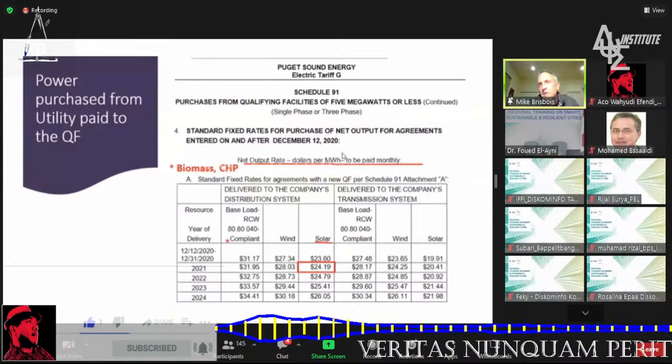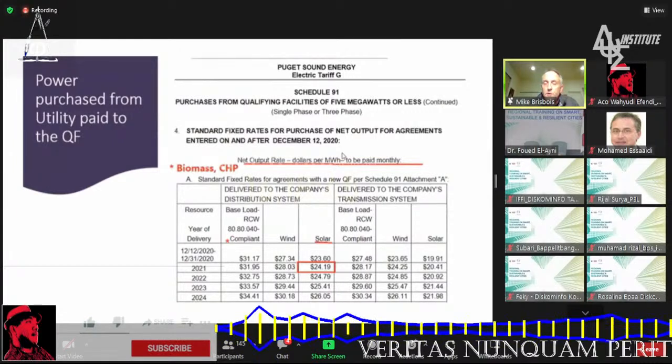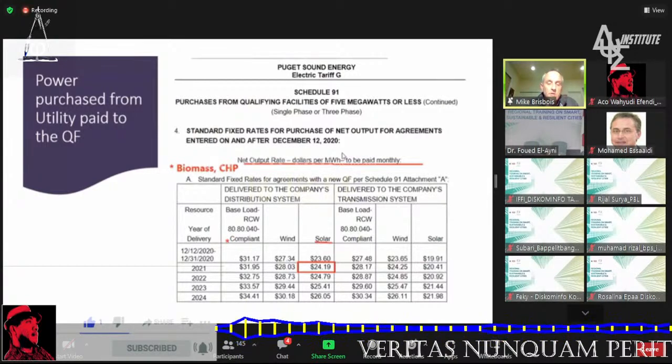And another thing is for your facilities, your sustainable facilities, how much power do you actually need? So we come in, we do an energy audit of your facility. There's some critical loads, like life safety. If it's a hospital, you want to make sure that those stay on. There's some optional loads. Do you need air conditioning? Do you not? Do you need heating during the summer? So we look at all the loads, and we kind of work with you to hash out what's the critical loads and what's not.